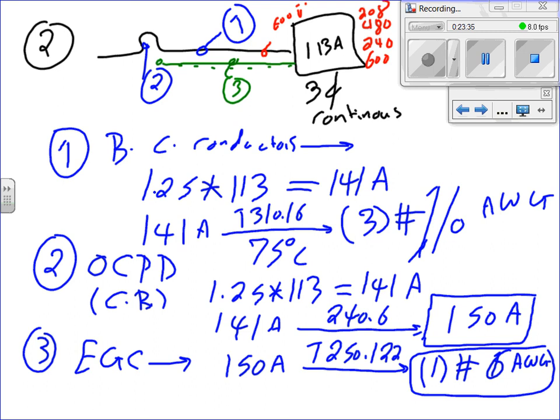But most of the time, guys, your choices in the US is between 208 and 480, 3-phase. And 208, usually, if your building is 10,000 square foot or less, most likely it's going to be 208. If it's higher than that, most likely it's going to be 480. So if your building is 480, you really have no choice except to use the 480. But if you have the choice, 10,000 square foot, generally speaking, or less, 208, 3-phase. Higher than that, it becomes 480. Any questions? Straightforward, no gimmicks, nothing.